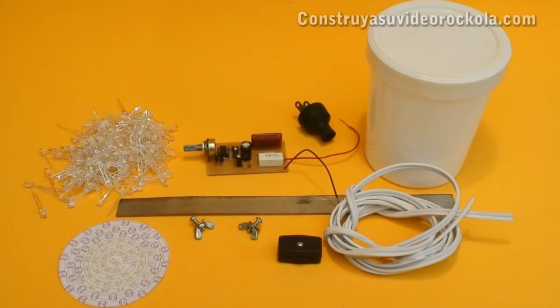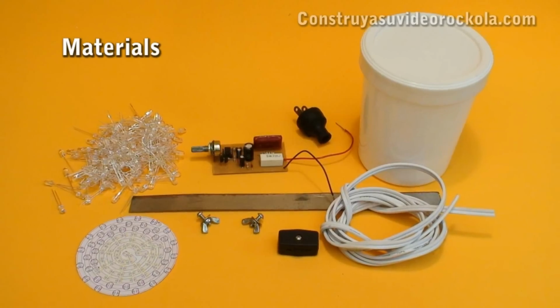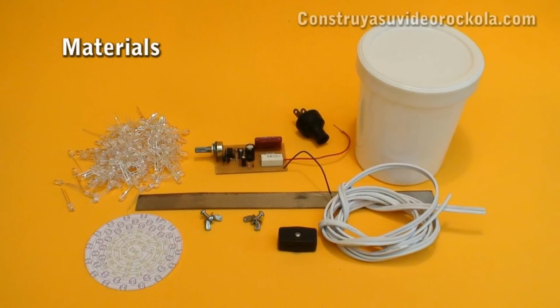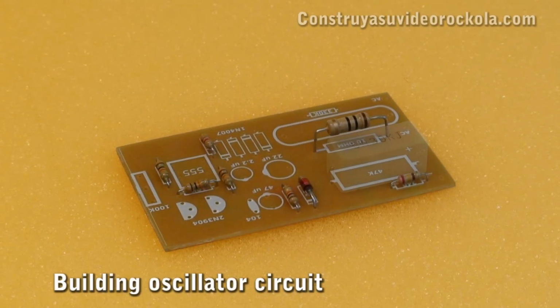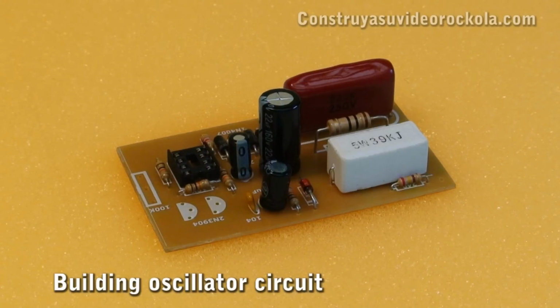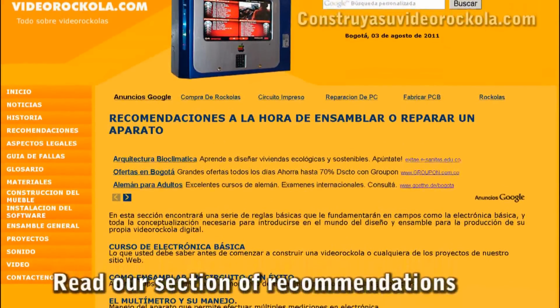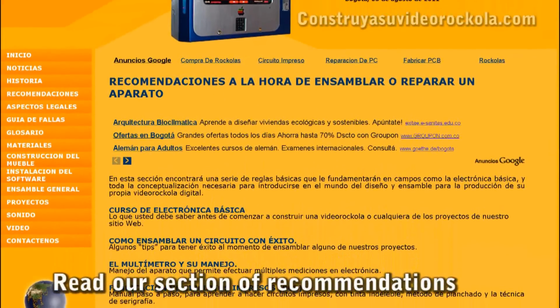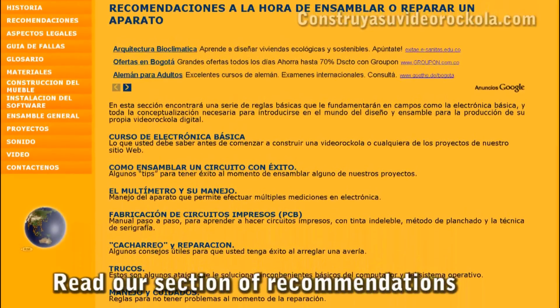Construction. After downloading from our website the PDF file with the list of materials, wiring diagram, and the PCB, we must begin to build the oscillator card. You should put all the components using the mask as a guide and review components thoroughly before soldering. If you have no experience in assembling an electronic project, be sure to read our section of recommendations.